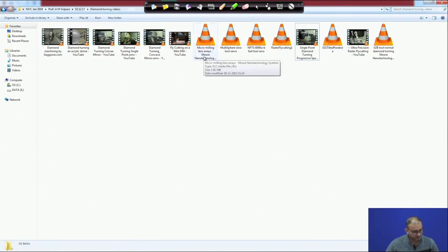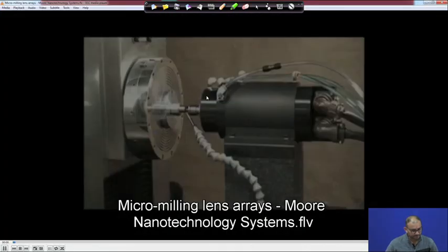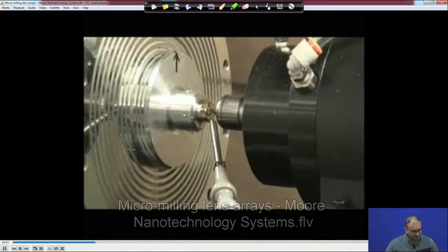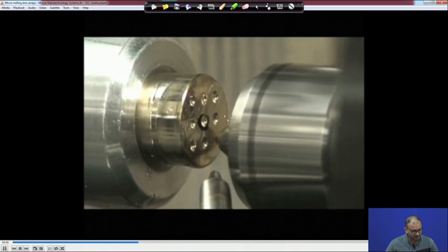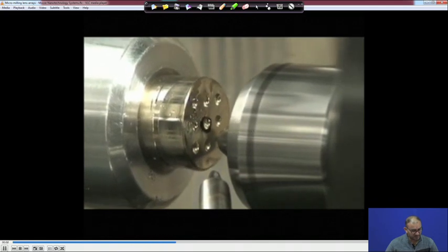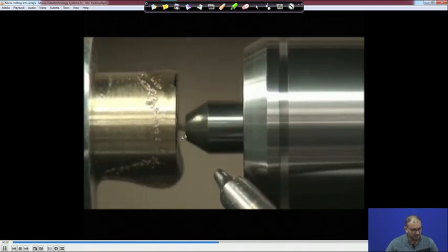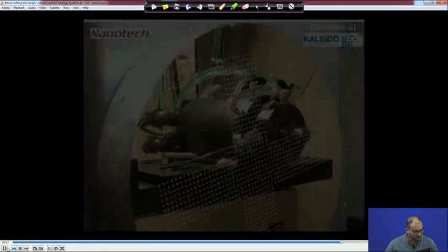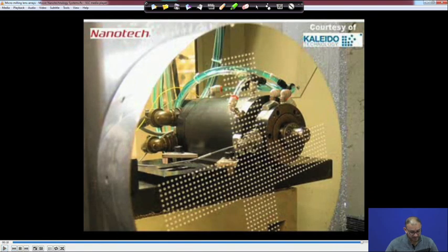And suppose you want to make something different. Here, this is fixed and the z axis is working in a synchronized manner. So, the tool is now rotating and you are making different types of lenses on the surface. So, this is the lens mold. After that, you can create hundreds of molds on a very optical grade surface, and then you do some type of polymer molding and you can get the required molds in mass production.